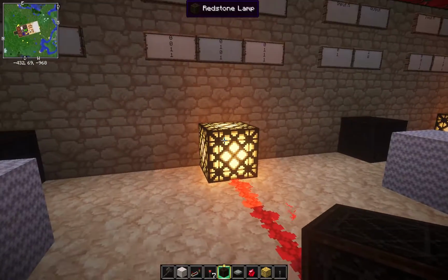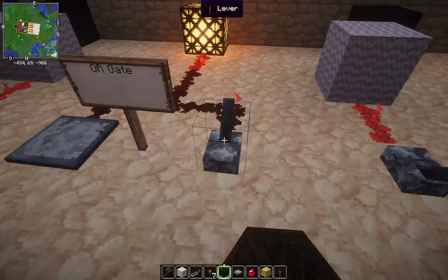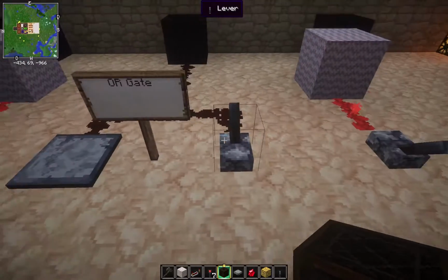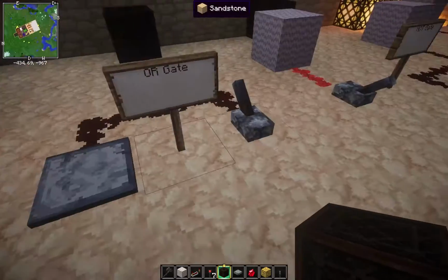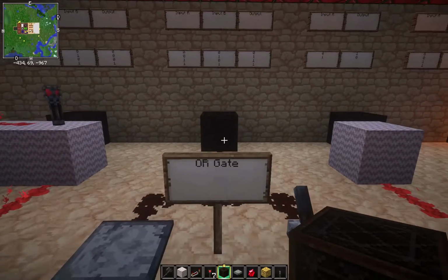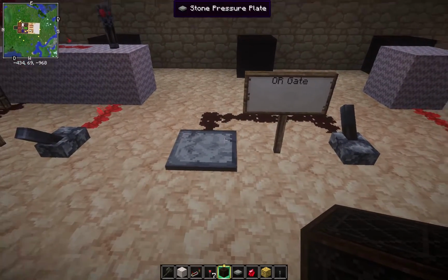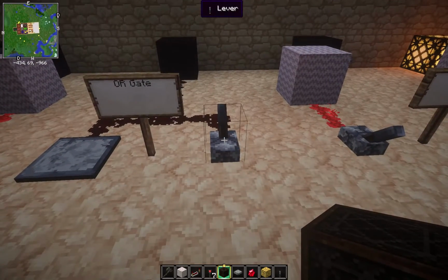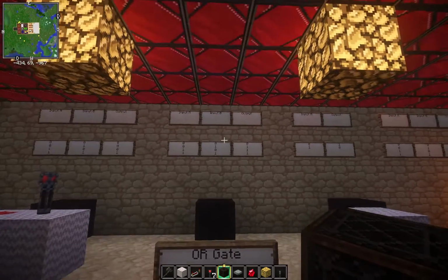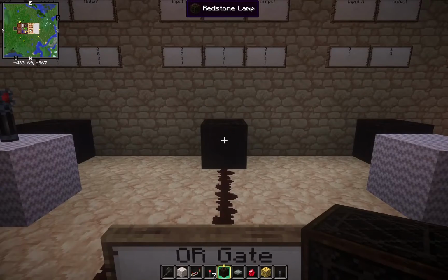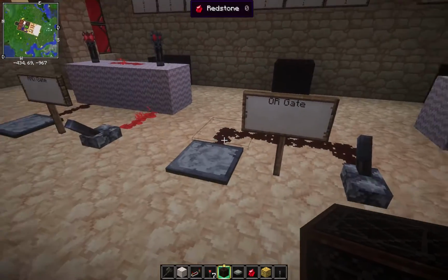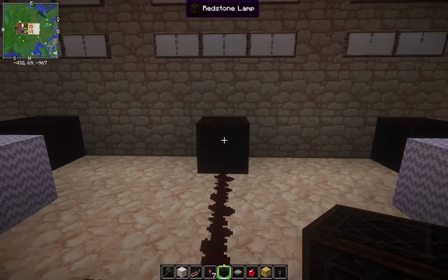It's still on. So the only time it's off is if input A and input B are both off, that's the only time our output is off. And we call this an OR gate because what we're saying is that it can be input A or input B on to generate an output that is on. So this or that equals this is turned on.